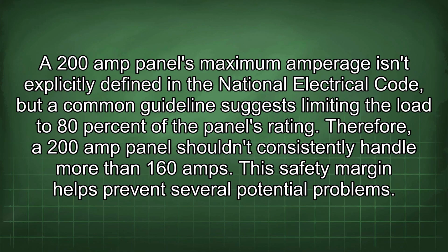A 200 amp panel's maximum amperage isn't explicitly defined in the National Electrical Code, but a common guideline suggests limiting the load to 80% of the panel's rating. Therefore, a 200 amp panel shouldn't consistently handle more than 160 amps. This safety margin helps prevent several potential problems.